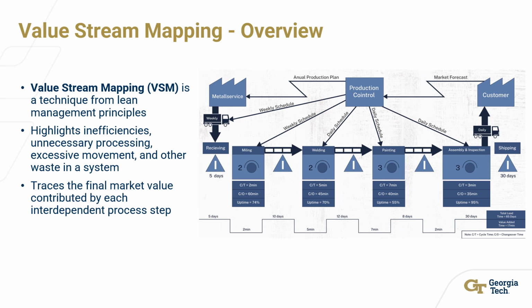Value stream mapping is a technique from the Lean Management toolbox for analyzing the material and information flow through complex processes. A series of interdependent processes are often required to produce manufactured goods. For example, manufacturing a smartphone might involve printing circuit boards, purchasing chips, molding the chassis, assembling components, testing functionality, packaging, and many other interrelated tasks. Value stream mapping highlights inefficiencies such as delays in component delivery, rework due to quality issues, or unnecessary processing. The central purpose of value stream mapping is to identify and reduce waste in core business value streams. Processing steps that do not contribute value to the final product should be eliminated.